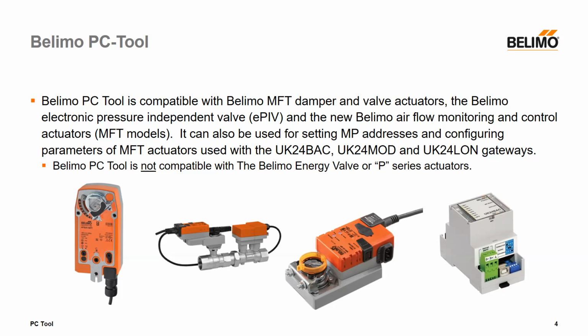The things that PC Tool are not compatible with, and this may be a little confusing, in recent years, we introduced the P series of actuators. So primarily on our butterfly valves, you'll see the PRK UP-3-T, but more commonly for modulating applications, the PRB UP-T-MFT. Now, although that P series actuators has MFT in the part number, it's not really compatible with PC Tool.